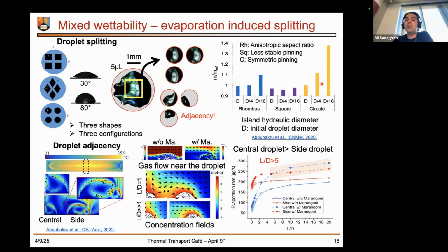One reason is due to the symmetry of the circular pattern. So as a result, we have the very good split of the droplets on the heated surface. On the square patterns, we observed almost no split of the droplets. The one reason is that the wettability that we tested on, which is 30 degree, is not too low to pin the droplets for the sharp corners.